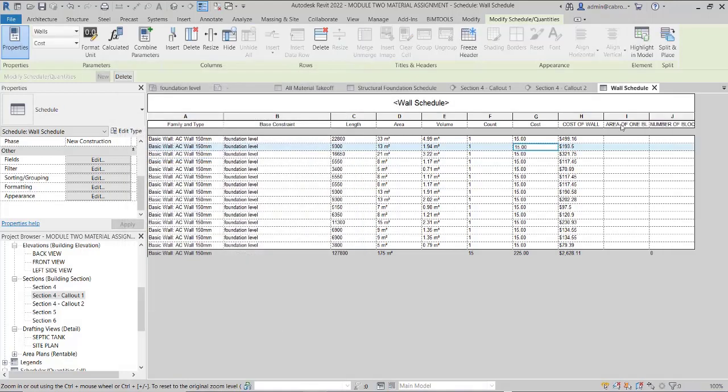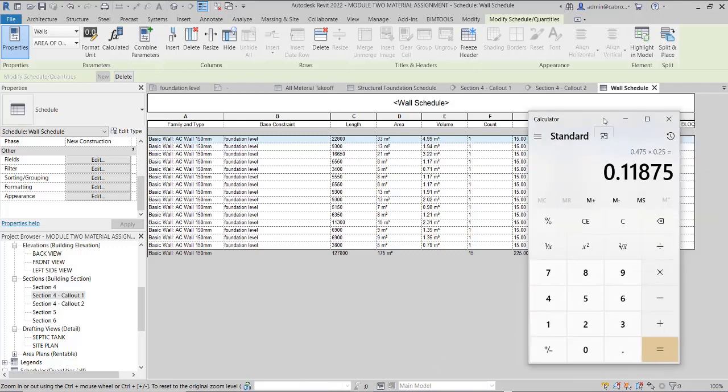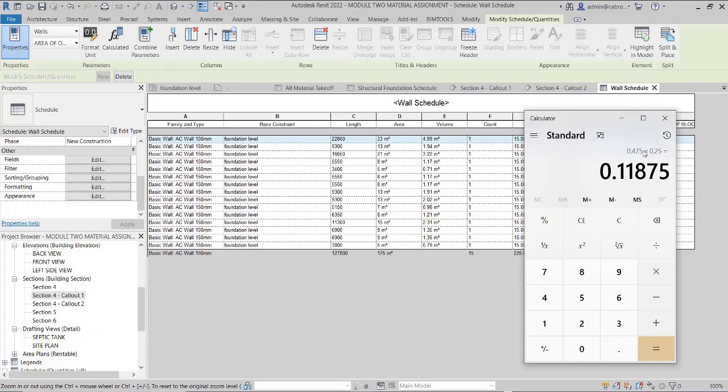we have area of block, and the area of block is a figure, so that one we consider a block work of 0.45 by 0.225. Then we add 25 millimeter mortar joint, it may be big, but let's consider 25 millimeter mortar joints to it.